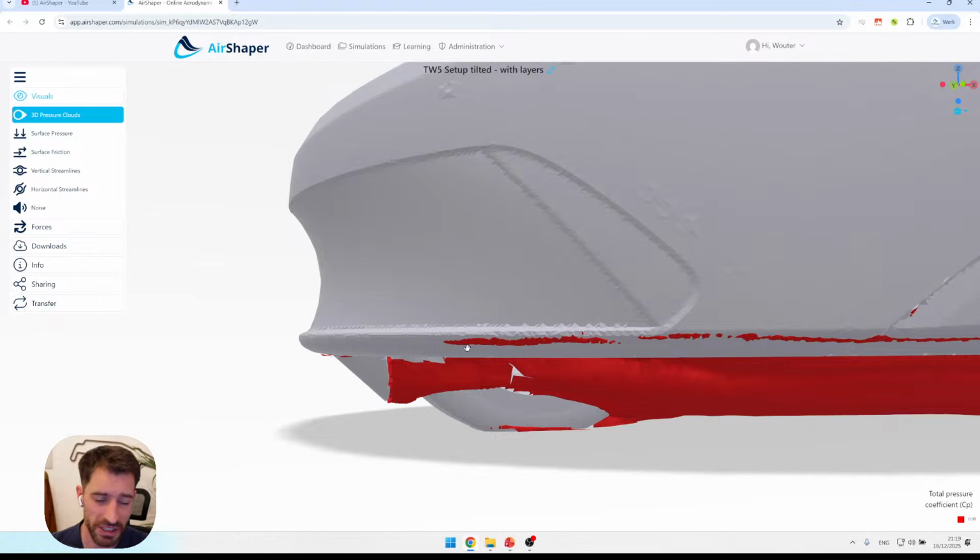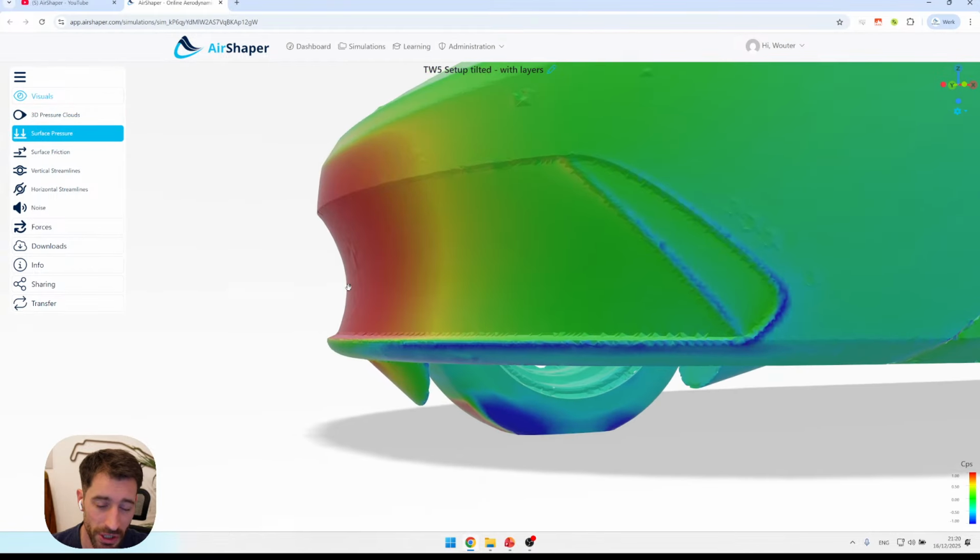So most splitters that we come across are flat plates sticking out, which is the main purpose of a splitter, because what you want to do is capture some of that high pressure on the nose, which is not just on the surface, it's here in the volume. If you stick out a plate, it's just like holding out your hand and scooping up some of the pressure which is acting on that plate, and that plate is attached to your car, so your car is being pushed down. That's the purpose of a splitter, at least on race cars.